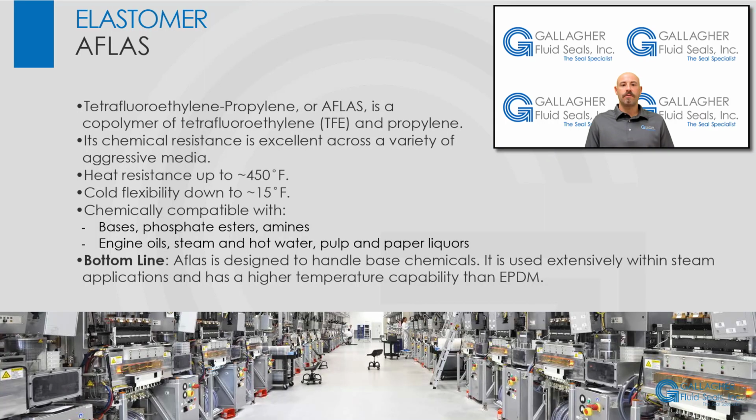Next is tetrafluoroethylene propylene, or AFLAS, which is a copolymer of tetrafluoroethylene, or TFE, and propylene. Its chemical resistance is excellent across a wide range of aggressive media. AFLAS offers heat resistance up to approximately 450 degrees Fahrenheit and cold flexibility down to approximately 15 degrees Fahrenheit.